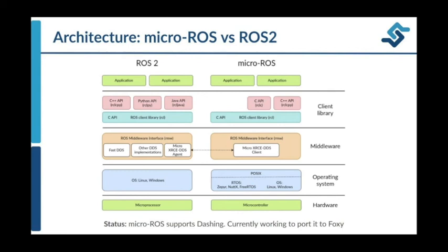So in order to be compliant with most of the embedded platforms and real-time operating systems, micro-ROS only partly uses the RCLCPP API of ROS2, but also provides a C user API, which is called the RCLC. And it is directly interfaced with the lower-lying API, which is another C API, present both in micro-ROS and ROS2, which is the ROS client library, the RCL.